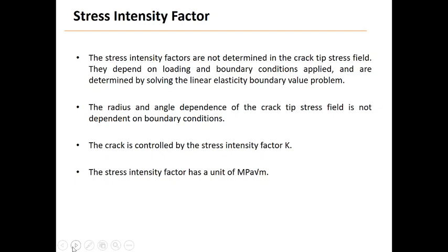In other words, the physical significance of this is quite remarkable, because you don't need to think about other things when you think about fracture. Just think about what the stress intensity factor is. If you can calculate it or measure it, then you know exactly what happens around the crack, because you know the stress around the crack tip, and that determines when the crack should go or not.